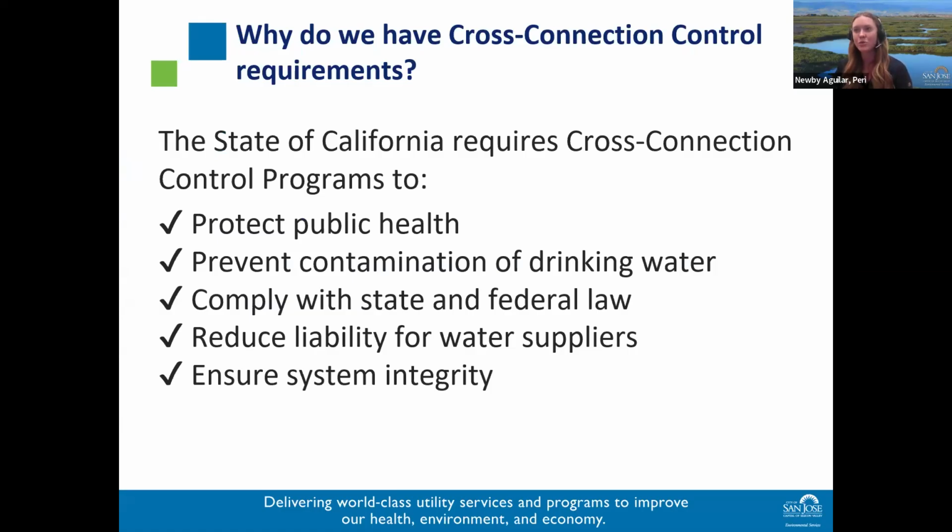We do have cross-connection control programs to help protect the main water supply and customers from potential backflow events. These programs reduce the risk of backflow events that could introduce non-potable water into our distribution system, and even small-scale contamination in a single property, such as irrigation runoff or industrial water processes, can potentially spread through a system if it's not properly controlled. So cross-connection control helps maintain stable hydraulic conditions and water quality throughout our distribution system by preventing the reversal of flow and intrusion of foreign substances and contamination.